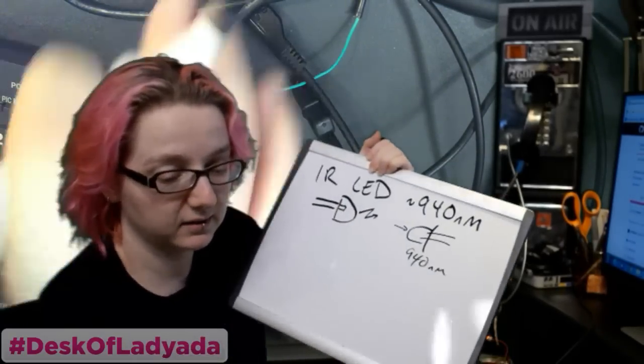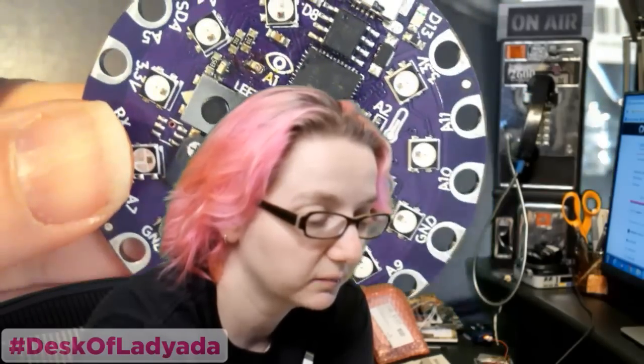And so when you look at, for example, the IR receiver and transmitter LED on the Circuit Playground, I can show that. They're really both just LEDs, just this one's black. It just has a filter on it. This one's black. That's the receiver LED, and that's a transmitter LED. Remember, IR light receiving and transmitting, it's the same PN diode. They're just built a little bit differently. This would be a very bad receiver, and this would be a very, very bad transmitter because it's got a filter on it. But they're pretty much just LEDs, and they're just tuned to that 940 nanometers.